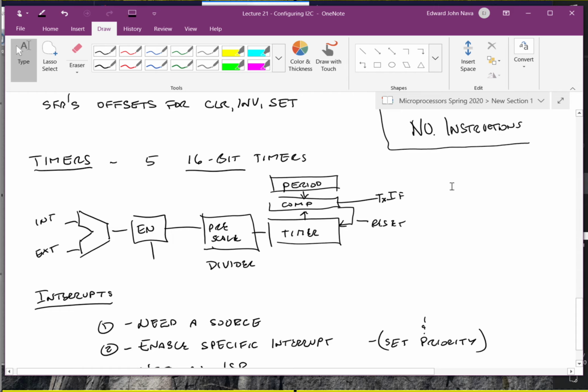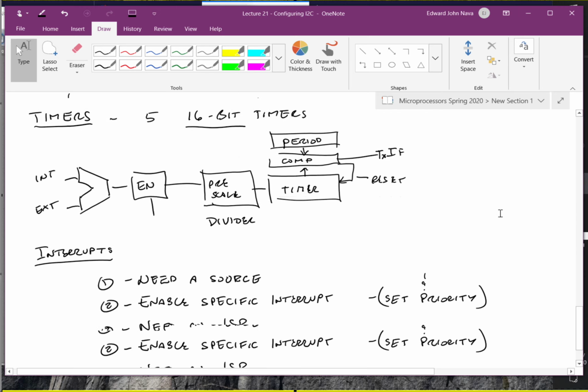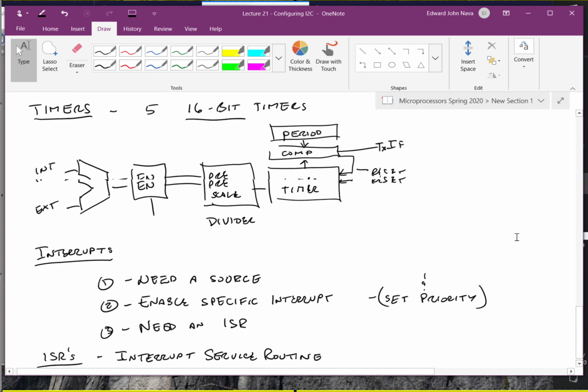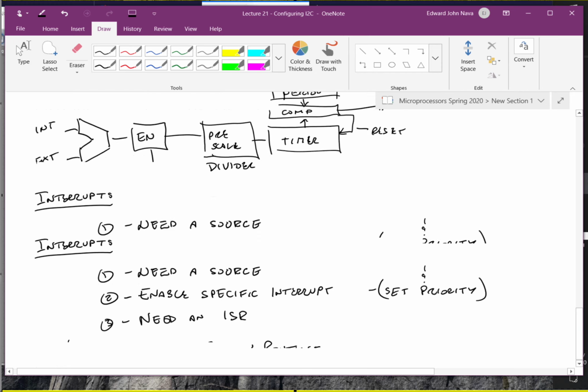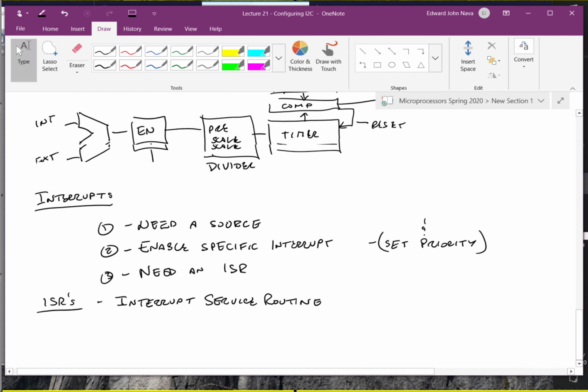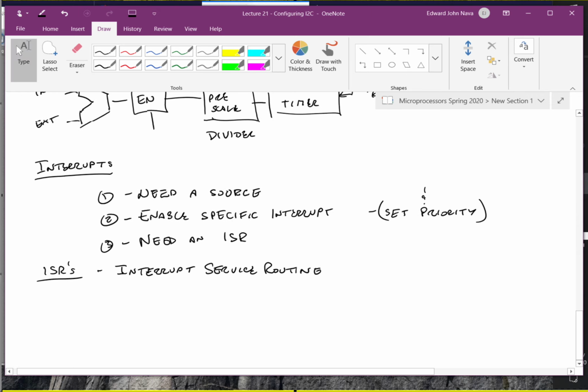Every time this heartbeat, the interrupt, goes off, it's basically a signal to start reading the sensors, doing your navigation calculations for that particular iteration. And so you would do that so many times a second so you can maintain accurate position and attitude information calculations.